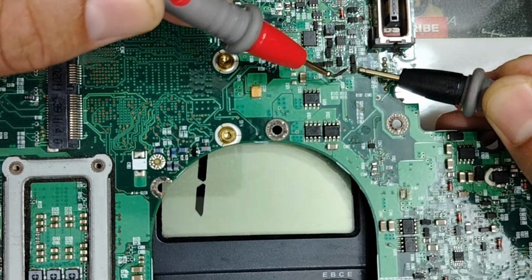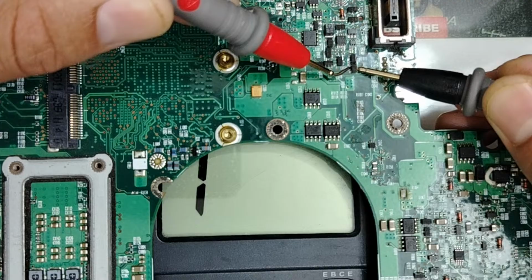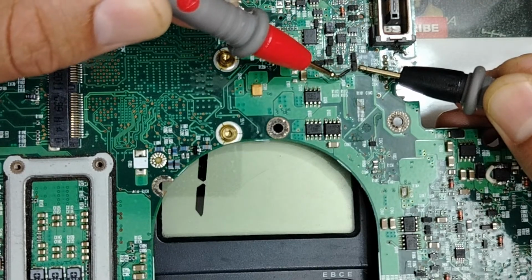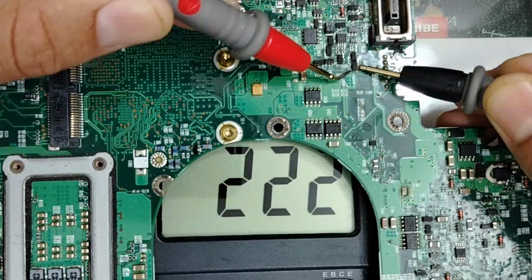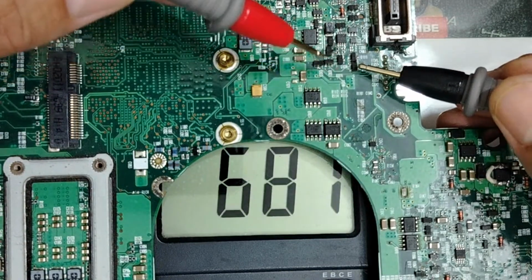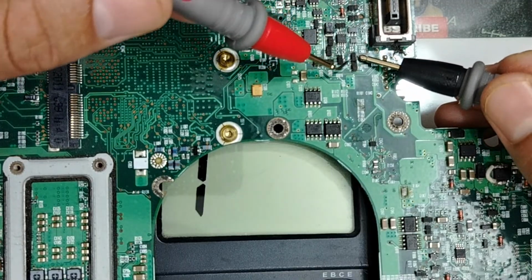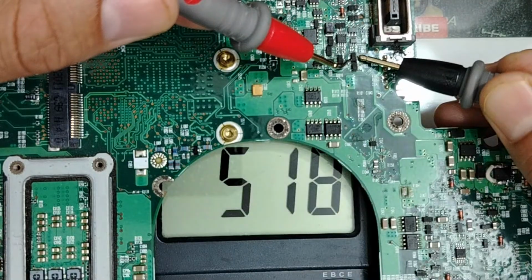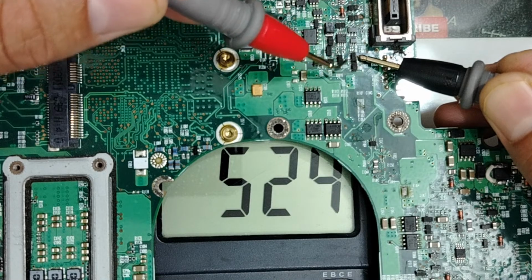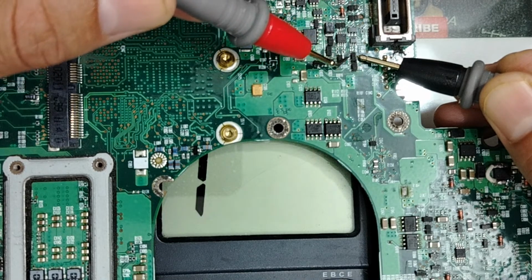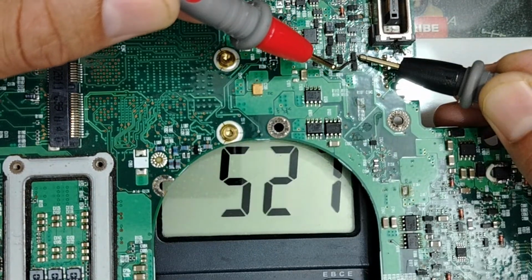But when I touch the gate using the red probe, I inject a little bit of current here, so I will get a short. Do you see, my friend? This is a short, but about just 2 seconds. Okay, so this MOSFET is good. Let's check this one also between drain and source. We get a reading about 500. If I inject a little bit of voltage here in the gate, I have to get a short.